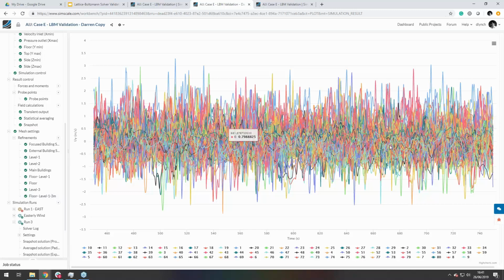The reason why it's so fast is because it's more of a Cartesian type mesh idea, where the mesh that's inside the buildings is removed, and the mesh that is in the fluid domain is kept. And it's a very high order accurate scheme that is used to find out where the walls are, and that is how, on a fundamental level, the LBM meshing works.